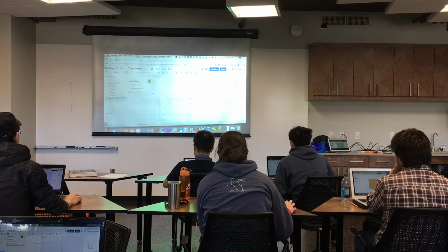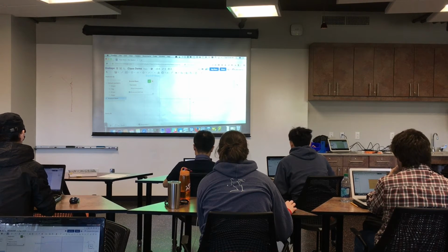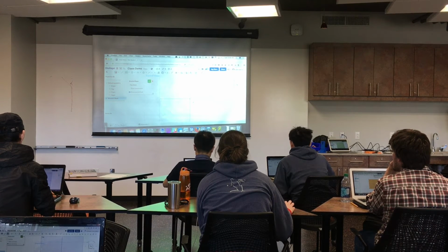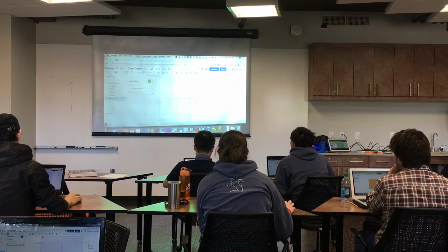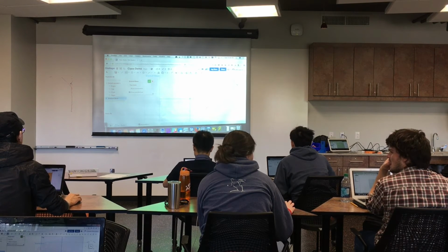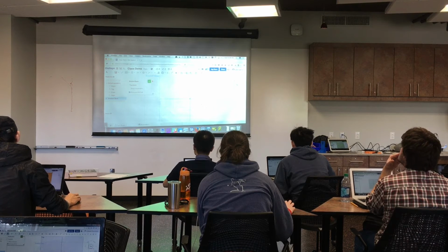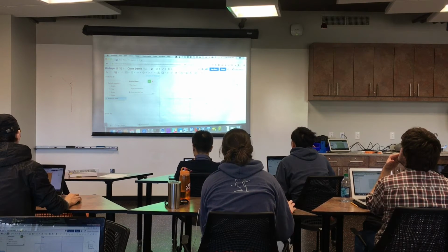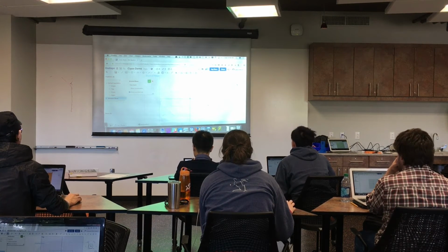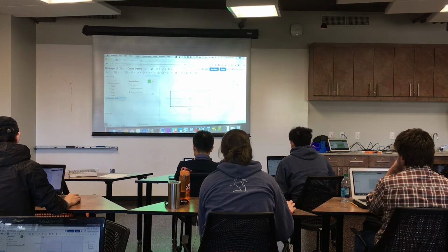And notice this little dot's the origin. When I hover over it, it gets yellow and it's selected, which means that I am going to constrain the center of my rectangle to be on the origin. So go ahead and highlight it and click. And you see now I can drag out a part. Don't worry about getting the dimensions of this exactly, or really even close, when you're doing this. You'll drive yourself crazy. So just drag out a shape and click.